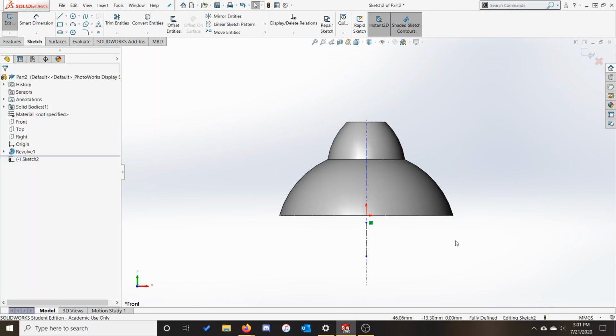You can get a temporary axis from anything that is rotationally symmetric. It doesn't have to be a revolve. Extruded cylinders also have temporary axes. In the end, this is going to result in doing the same thing as if we had drawn our center line coincident with the origin and set to vertical, but on some occasions this methodology can be more reliable.